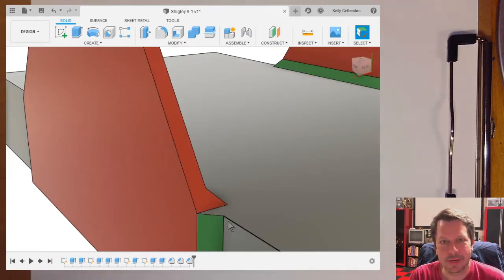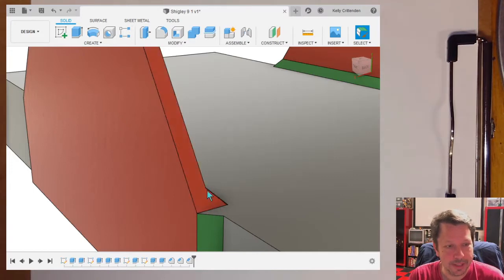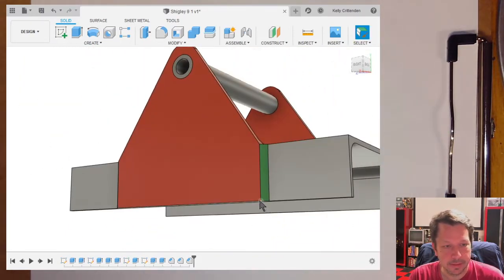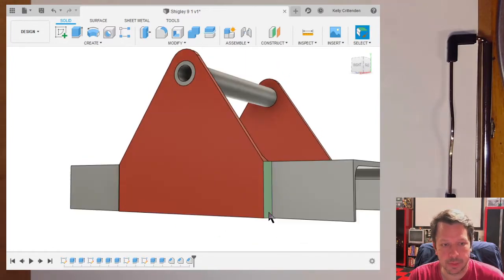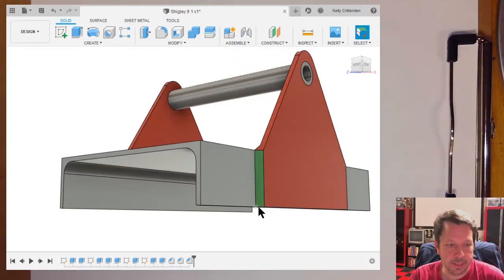I didn't bother trying to model that in Fusion, but technically there would be some weld going across there that we're kind of ignoring. Although that is a corner, and usually the corners of weld groups are the important parts. So we're not going to completely ignore it, because the corners are usually pretty important in weld groups. So the ends down here and the corners are going to be the places of interest where we calculate the shear stress. So we'll calculate down here. I think your book calls this point A. Yes, point A, and then point B is over here.